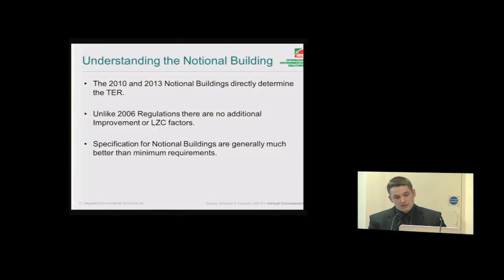In fact, that fixed approach is the methodology implemented in Scotland's Section 6 calculation method, where we're now at a point where, to meet the current Section 6 regulations, you're looking at knocking off about 50% of the energy consumption compared to your notional building. And there really isn't any guidance as to where that savings should be made. It's a huge chunk of energy to try and shed. In a lot of buildings, perhaps something like a hospital, most of the energy consumption is attributed to things like central plant rather than heat loss through the fabric and infiltration. It can be really difficult to shed that level of energy.